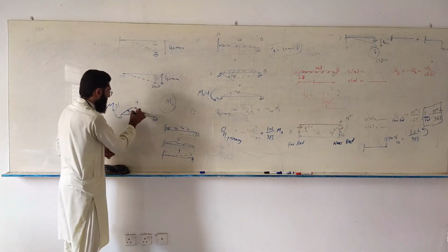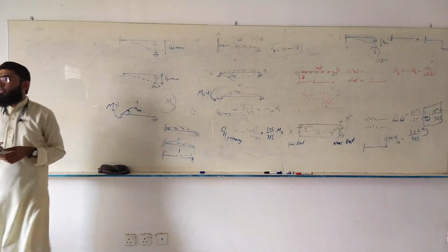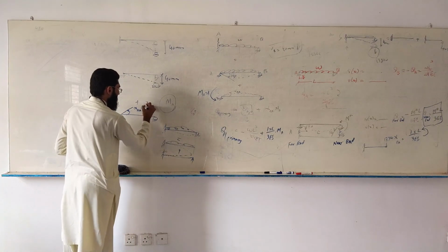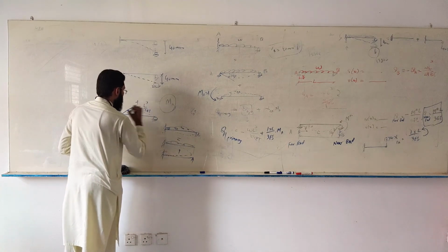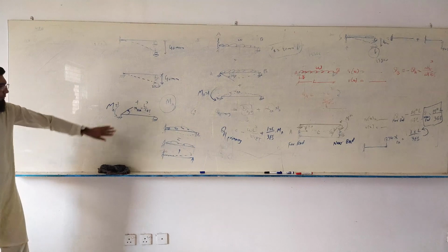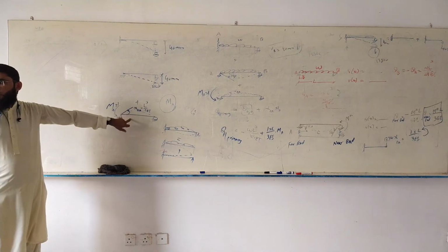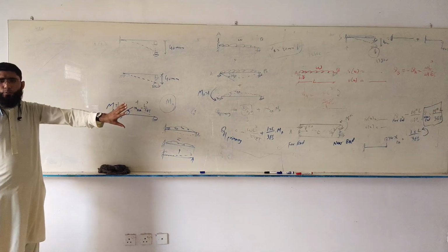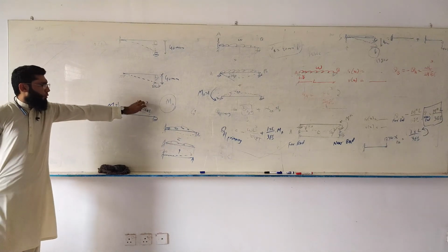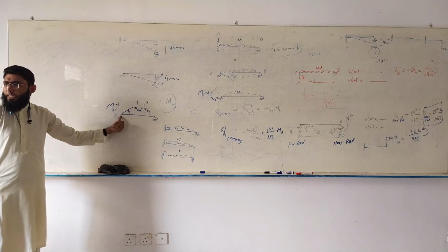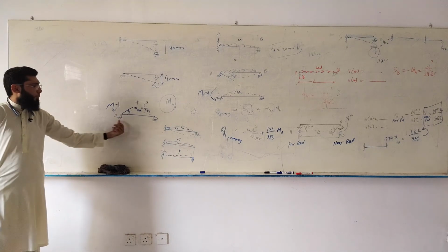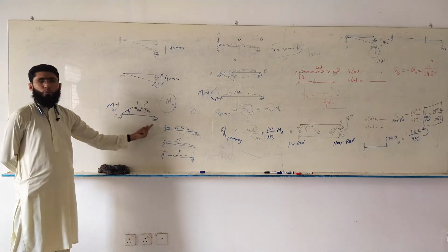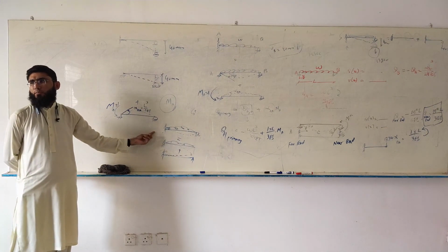Alpha AA equals L cubed over 3EI, and in the same direction as the unit load over here. Getting it? So, the best way to use the table is to figure out the magnitude, considering whether it's near end or far end. And the direction is governed by this. Do it for the near end, and for the far end, the magnitude gets halved and the direction changes.